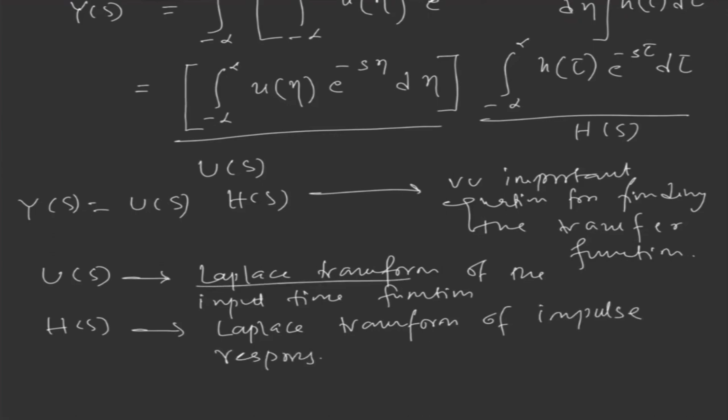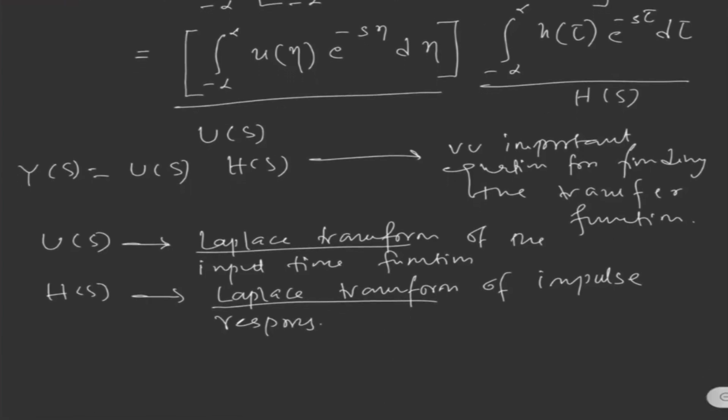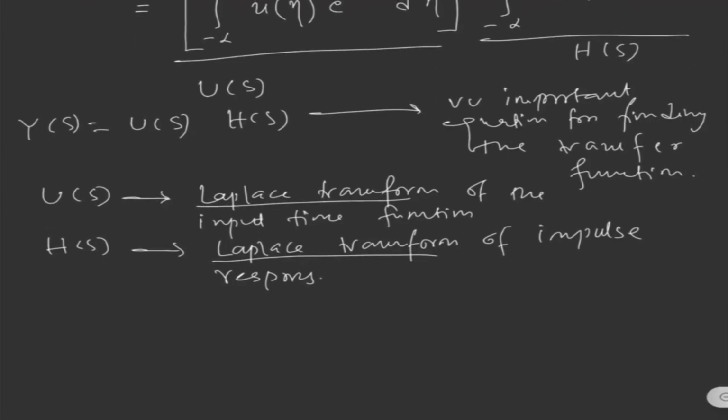We have to use this when we are talking about the transfer function: we write the Laplace transform of the response. So by this operation, the complicated convolution integral is replaced by a simple multiplication of the transforms. Now we need to interpret what we have done here, and how we can come up with a better understanding of the transfer function.